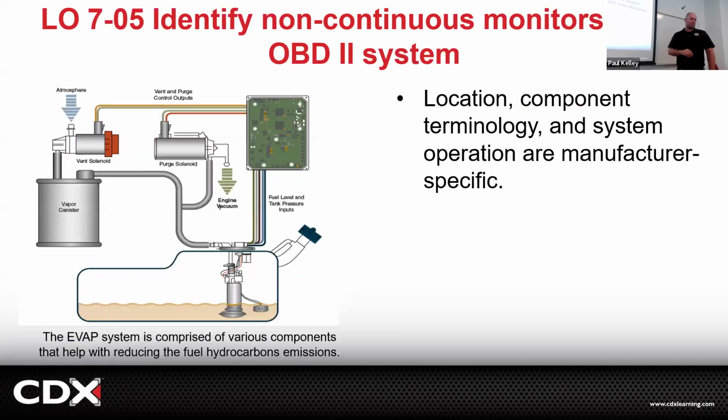So when we're looking at, for example, the evaporative emission system, this is a cause of many codes. What do you think the most basic cause of an evaporative emission system leak is? Gas cap. But see, the code didn't say gas cap. And I'm going to say that problem right there is one of the main reasons that people are really sketched out by automotive. It's like, hey, you've got a check engine light on.